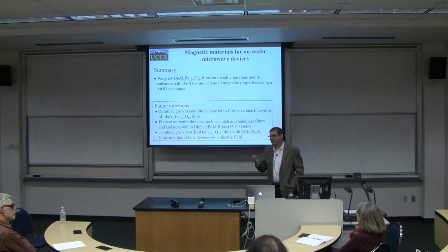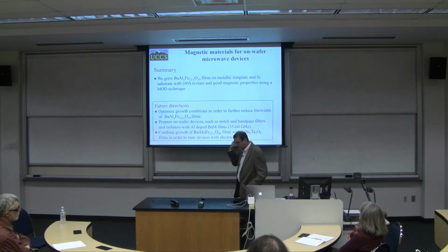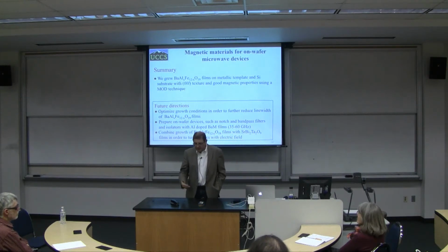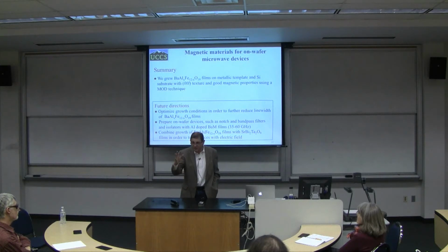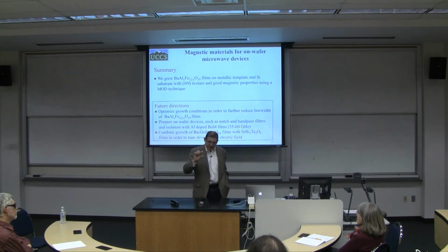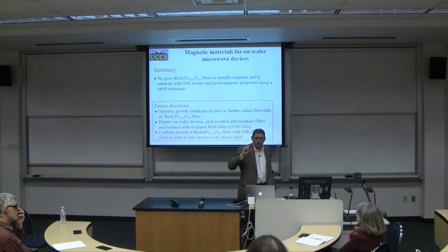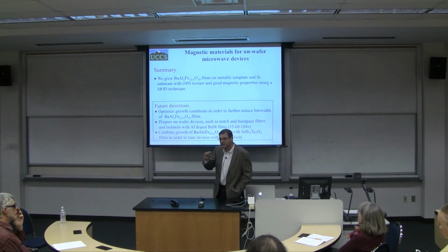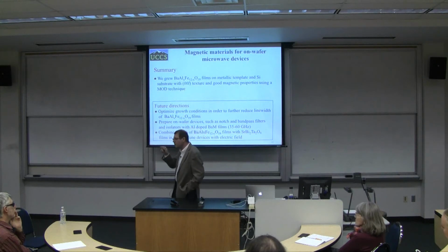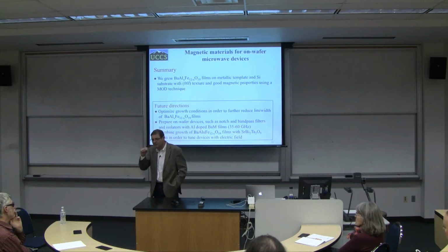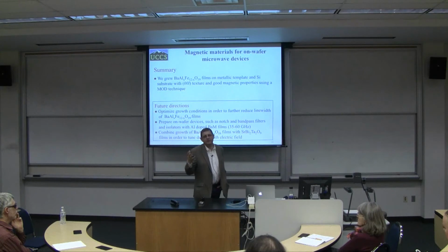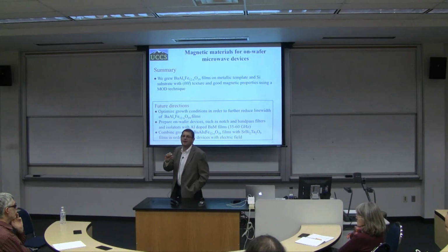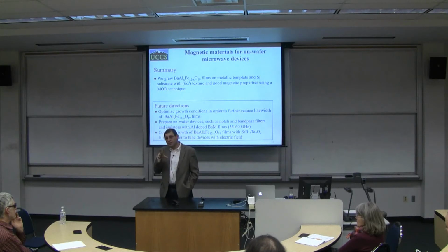You know that if I'm sending an electromagnetic wave towards a metal, the wave is going to penetrate to a certain depth and then is reflected. The skin depth, this penetration depth, is determined by two parameters: conductivity and frequency. Both enter as the inverse of the square root of the conductivity sigma and frequency. So the higher the frequency, the thinner the skin depth is. The smaller the conductivity, the bigger the skin depth is.